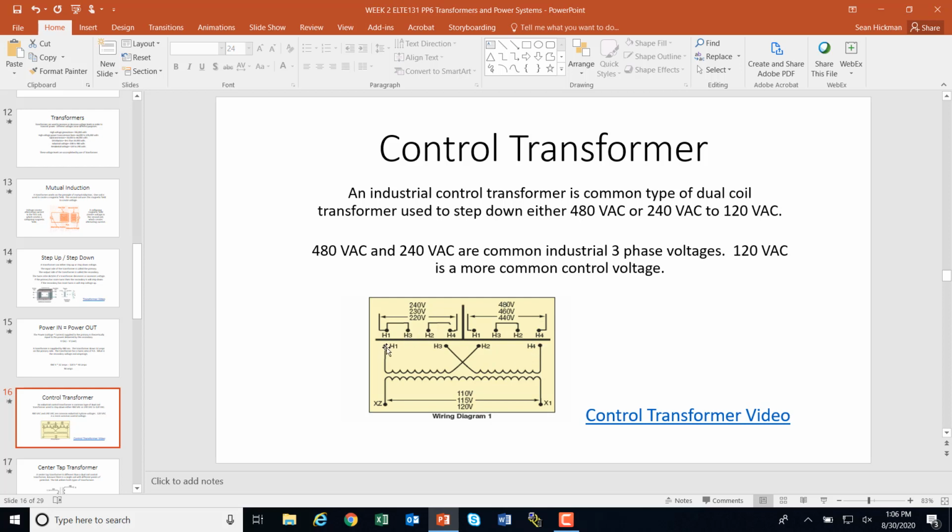So there's your voltage between H1 and H4, and that's what it's showing here at 460. Then we do a jumper across H2 to H3. Basically we've taken this load and run it in series with this load, so we've made this coil of wire and increased the turns on it quite a bit.